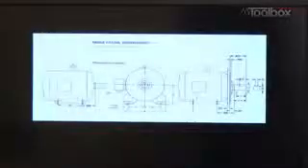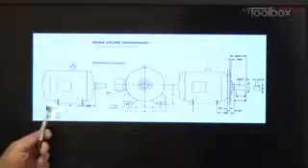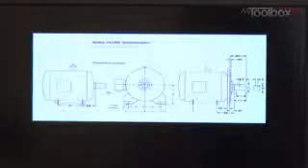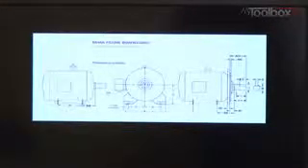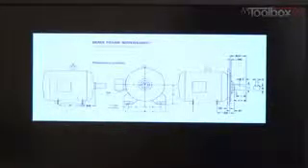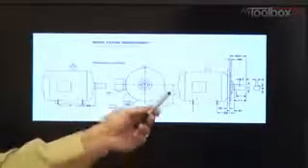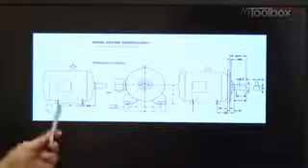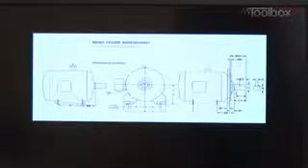Here's what the accompanying drawings might look like with that frame size chart. I realize it's kind of hard to read on this video, but you'll find these in motor books. You'll find them in NEMA books. These are NEMA frame dimensions. NEMA is the National Electrical Manufacturers Association, kind of the police on the motor nameplate data. Different dimensions, like here for one, for instance, is dimension D, and that's the shaft height. Dimension 2F is the hole pattern lengthwise on the motor.